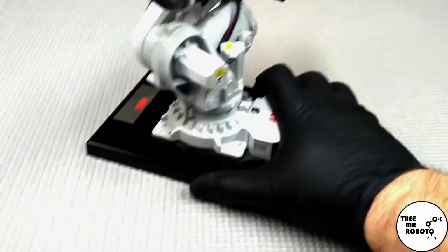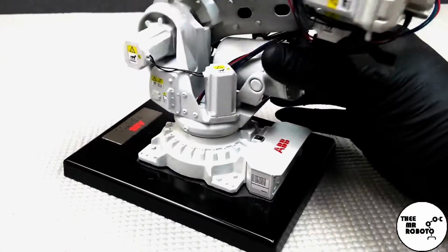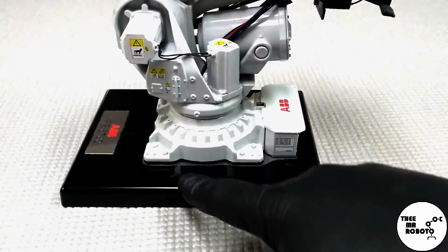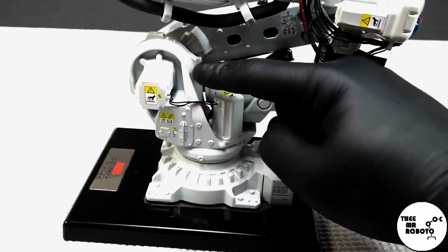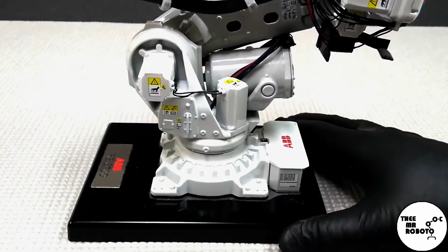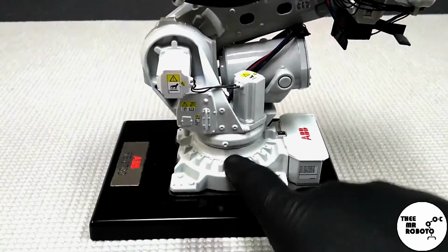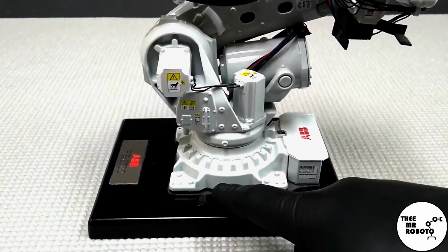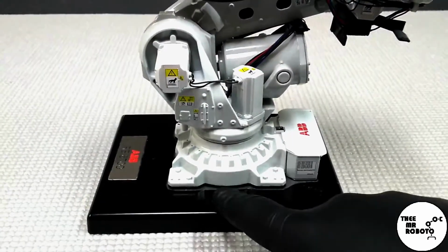So there is a theoretical coordinate system right in the middle on the bottom of this base, okay? Now, some robot manufacturers don't put it so low. Some of them will put it up higher in line with this axis. I'm talking to you, FANUC people. But for the most part, think of your world coordinate system starting in the very middle of your base and perfectly centered on this bolt pattern right here.